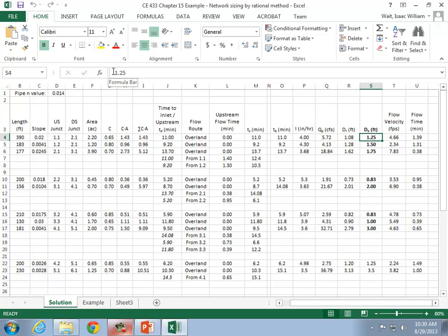QN and QP, where do you see QN? In the equation down the bottom, D or... Oh, Q is the flow rate, QP, yeah, and then N is the N value for the pipe. Oh, yeah. Q times N. Okay. Right, yeah. So N here isn't a subscript. In this example, what we're assuming is that the N value of the pipe is 0.014. That's at the top.